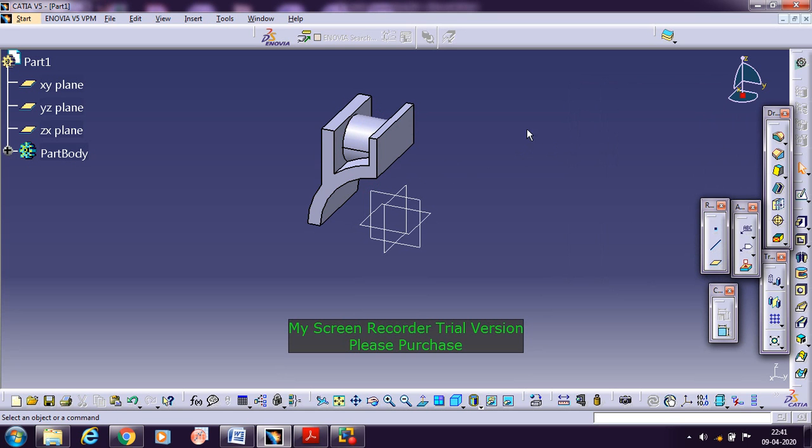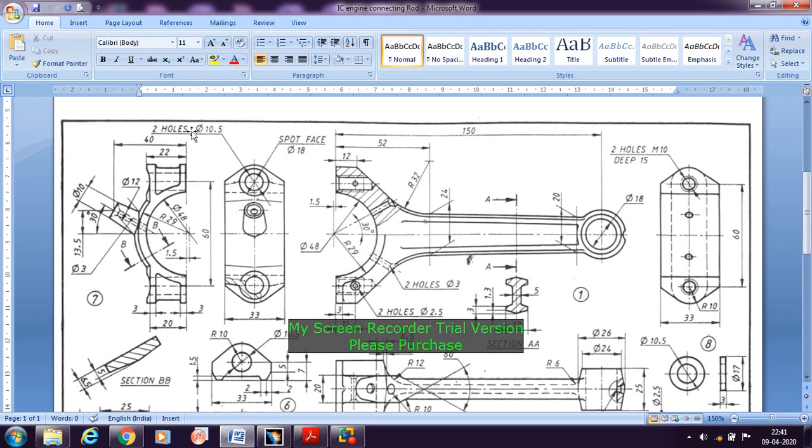Now, I need to drill a hole here, with a diameter of 10.5. It's a simple hole. There is no threaded hole because M is not mentioned anywhere here. The metric unit is mentioned elsewhere, but here only a simple measurement is given: diameter 10.5. You need to provide a simple hole.